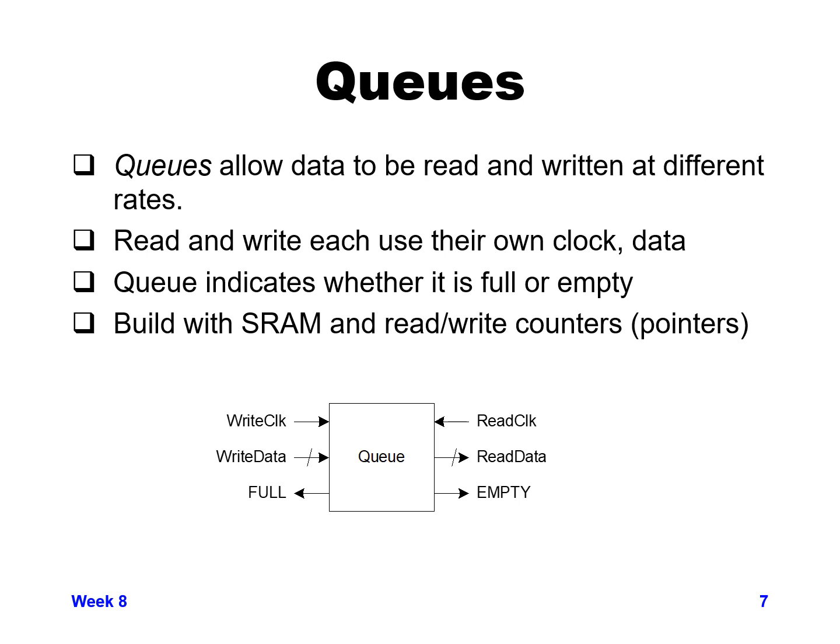In addition, whatever's reading out of the queue has to know whether there's data in there or whether it's empty. It doesn't necessarily on either side need to know how full or how empty. It just needs to know that once it's completely full, you can't write any more values, and if you're trying to read, once you're completely empty, you can't read any more values. So those are a minimum of the types of control signals that you need for a queue.